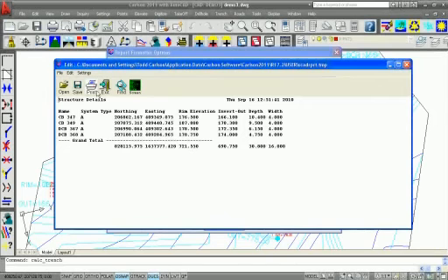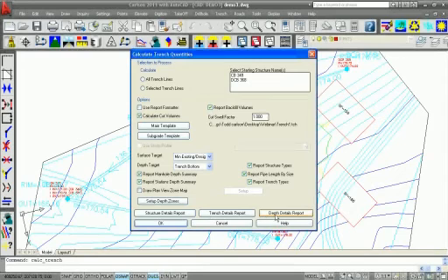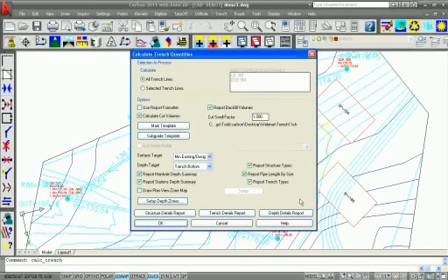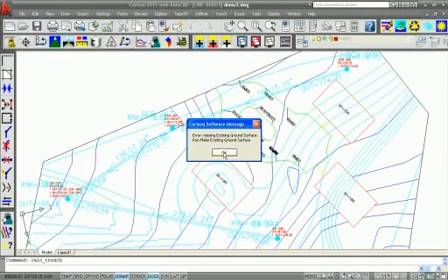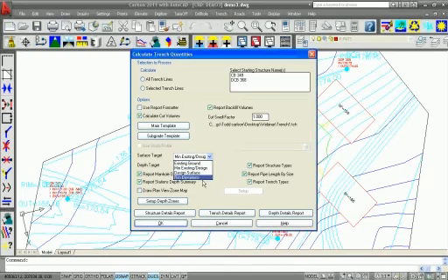And totals for that. The new report that I like and think will be very helpful is the depth details report. Let's do it on all structures. And for this, we're going to need a surface, I think. Unless, okay, let's do rim elevations, all trenches.